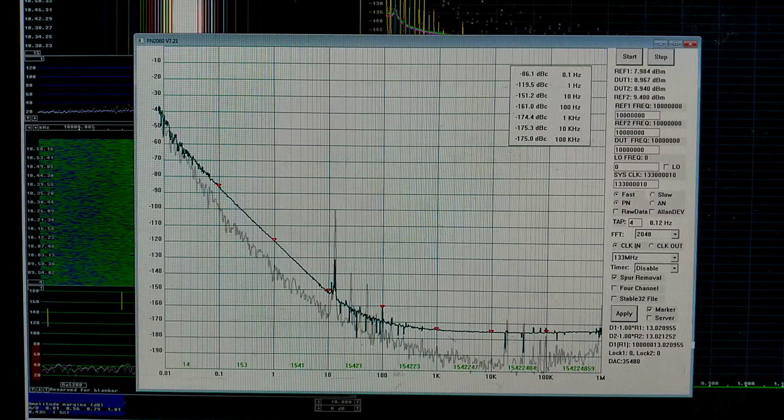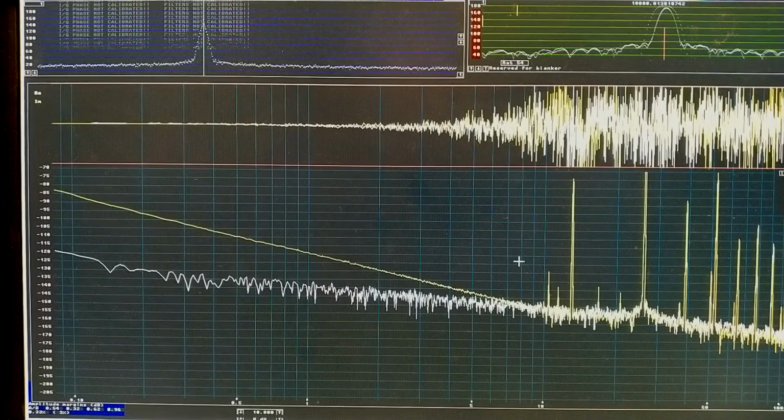And that's nice. Here is phase noise and amplitude noise in the same graph. You can see the phase noise here is far above the amplitude noise. And up here you see the correlation, and it is 0. So the small level of the amplitude noise is uncorrelated to the phase noise. And only at the beginning do I really have the amplitude noise. Then it is just a measurement uncertainty, because the time is not long enough.